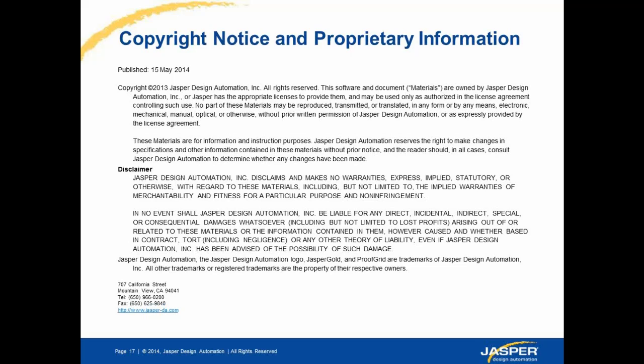Okay, but that's presuming you've done a complete verification. Yeah. No, because a bounded proof is far more valuable than hundreds of simulations you have done. So using the coverage metric that you have extracted from the bounded proof, you can actually sign off on the effort you have done.